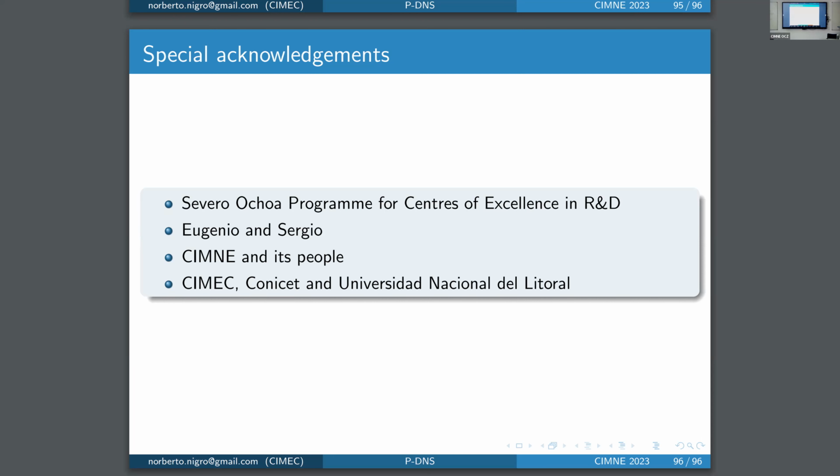You know, my concern is that you cannot have a method with a smaller computational effort than LES. Why? Because if you claim that you have an accuracy similar to LES, it is because you have entered the inertial range of the global energy cascade. And if you enter that, the big problem is that you have a limitation in the mesh size. So the wave number that you want to capture has to be 1/h, essentially. And if you want to reach a certain wave number, your h has to be such that 1/h is that wave number. You understand what I mean? Yeah. So this is, let's say, a showstopper. You cannot go better than that.